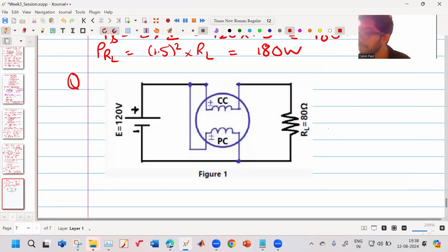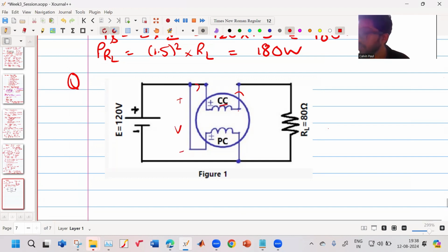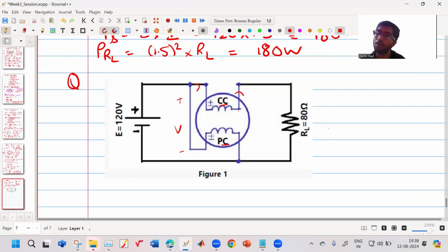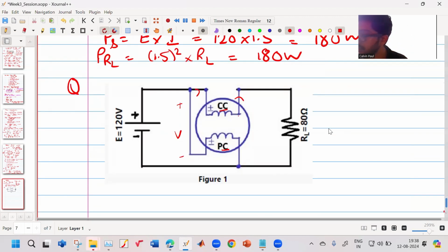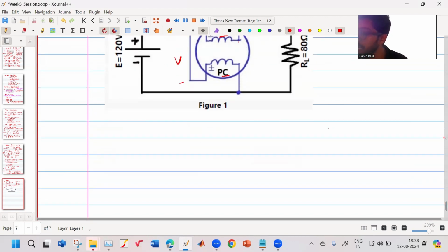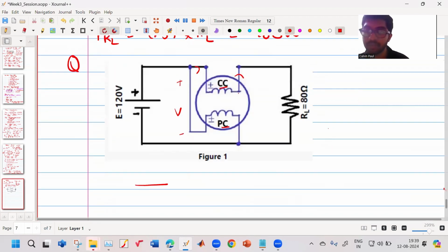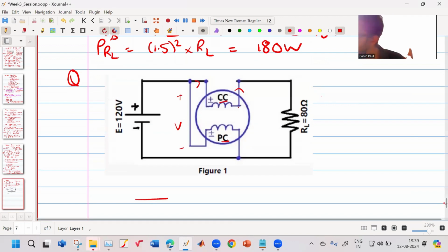Okay. Now, this is where the current is flowing. So this is the current and this is the voltage which is applied. There's a current coil and there's a pressure coil, and these together form your wattmeter. So your wattmeter shows the average power. So now, effectively, how does this circuit look? Let me draw it by the side of it.